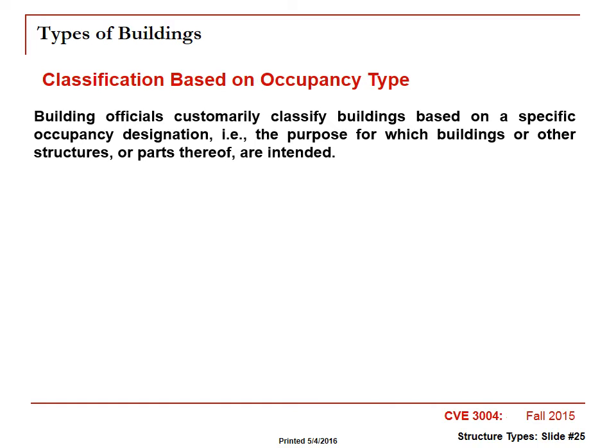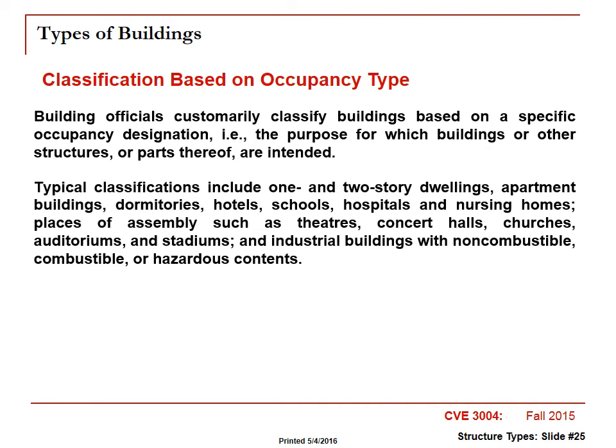Occupancy type gets to the purposes, but it really gets to the concept of how things are actually occupied. An office building, for instance, is going to have a certain live load applied. We do not look at the number of people, like people all weigh 200 pounds and there's X number of people on a floor. What we do is we look at typically uniform live loads.